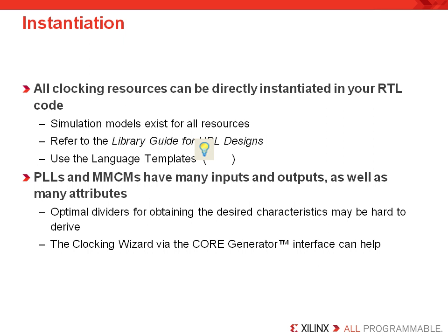Now, all clocking resources can be directly instantiated into your RTL code. The simulation models exist for all these resources as well, so behavioral and timing simulations are fully supported. Refer to the Xilinx Libraries Guide for HDL designs, or use the language template, for more information about how to instantiate or more details about the library of components.